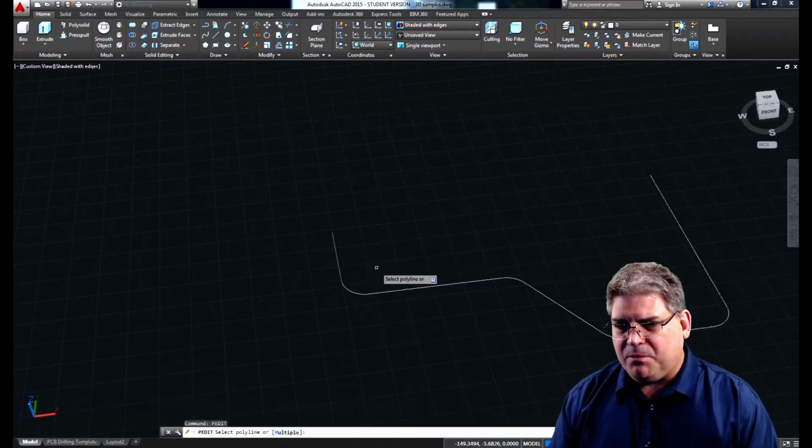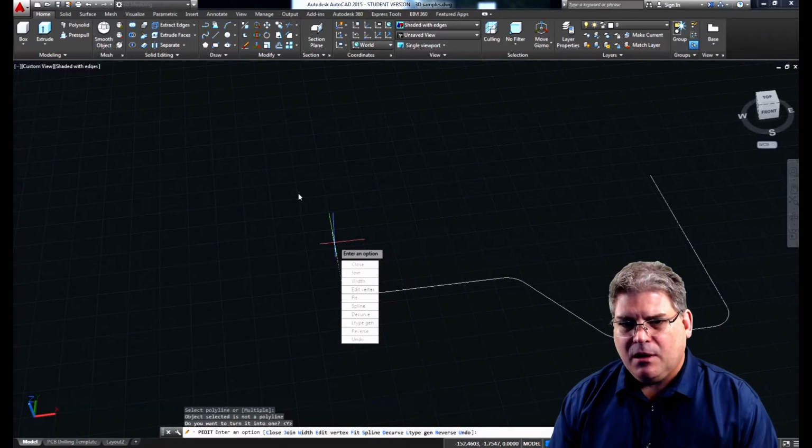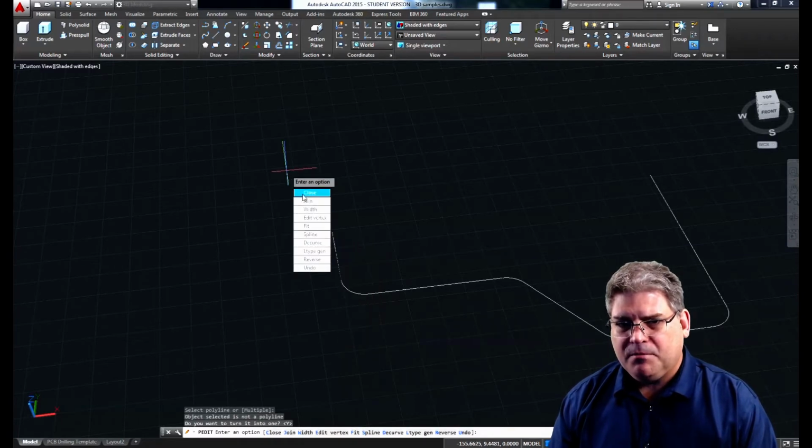So now we'll use the PEDIT command again to turn this into a single entity, and we'll do that by joining.